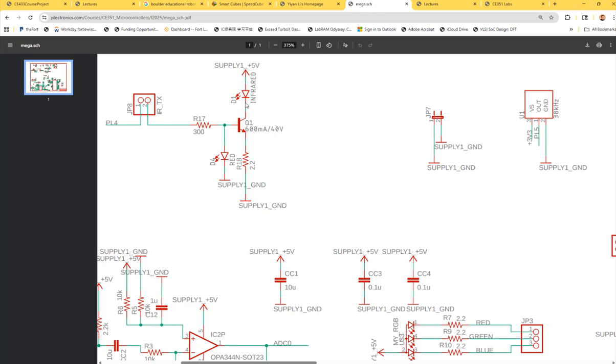We know it works. We can use only the receiver, the decoder on the functioning board, but use the emitter here. So this guy emits, and the functioning board has a functioning receiver. Then you connect USB to the computer, let this guy emit, and see if the functioning receiver receives anything.